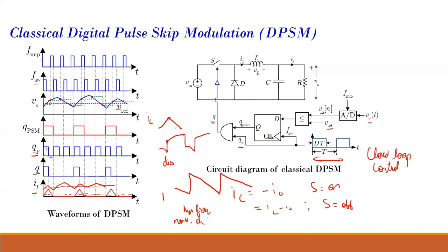Because there also, if we sense at that peak point, we will have more noise. That's what they say. Actually, why they say sensing at the peak point is noisy is that there will be some ripple. These are not shown in these waveforms, which are idealized for understanding. But in an actual converter, it turns on, and because of the diode recovery loss, etc., there will be these oscillations also.